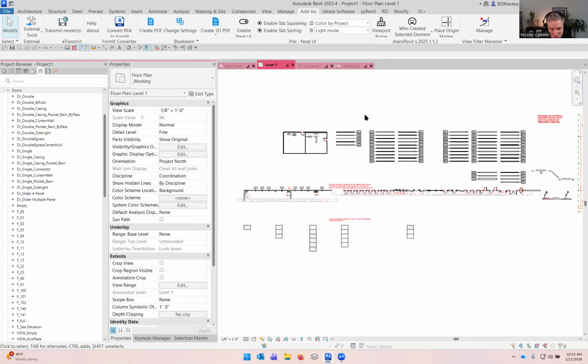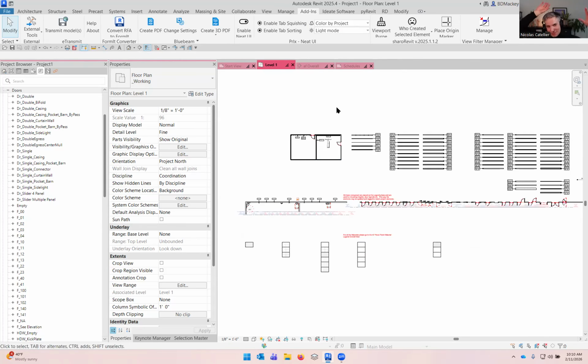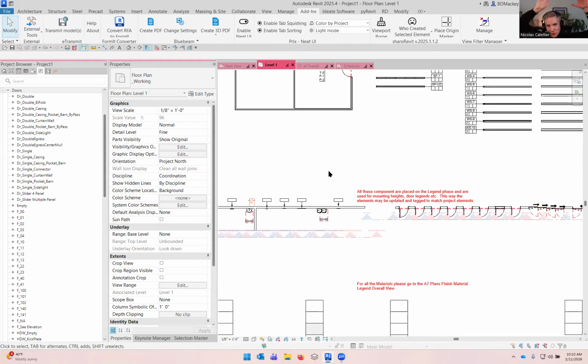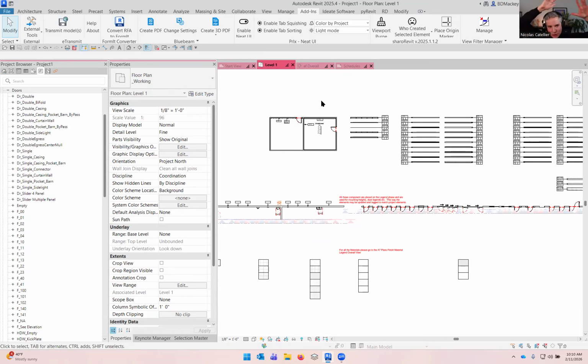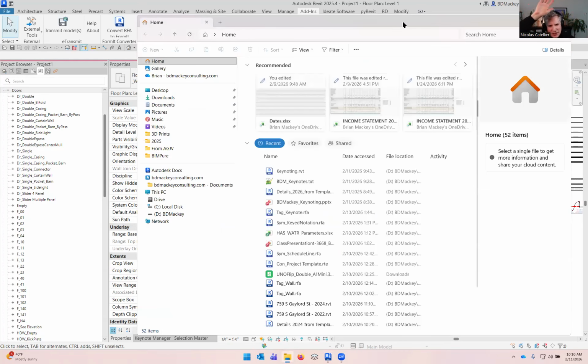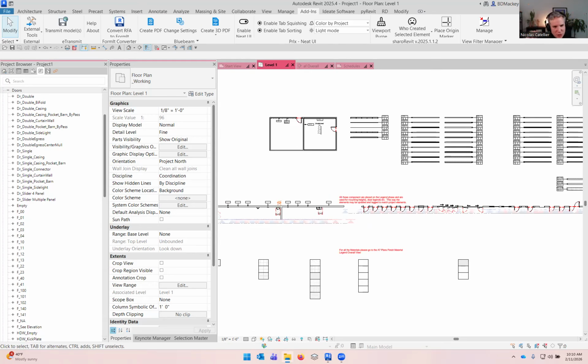So I think we could return to keynote tags and symbols. What we've concluded so far: tags are your preferred option for detailing. When it comes more to plan views, symbols can work, but you prefer keynotes, and you wouldn't use tags. So can you do a recap for all kinds of views, what system you would recommend?